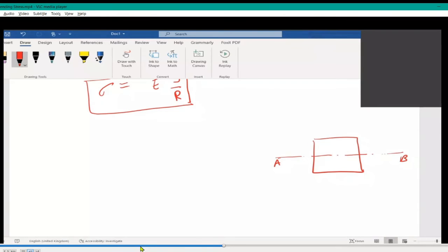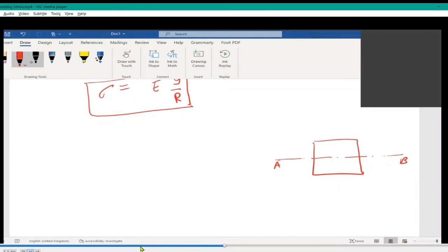And then if you look into the stress distribution like this, above the neutral axis, it will be like this. All values are like this. And below the neutral axis, it will be away from the member, acting outward. So there are two different directions of stresses acting in the element, above and below. One can notice two types of stresses. That's why you have the hogging type, which is compression on top and tension at the bottom.